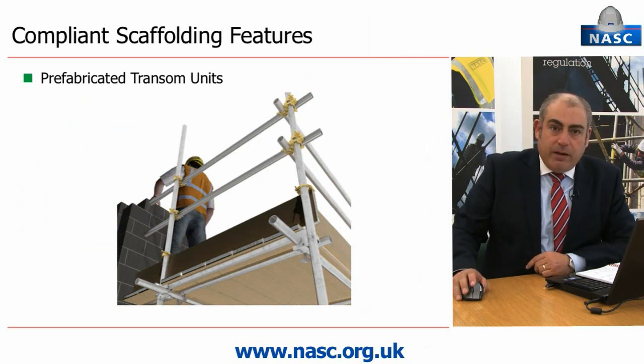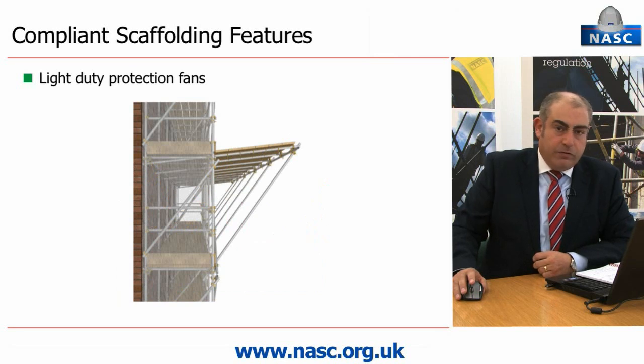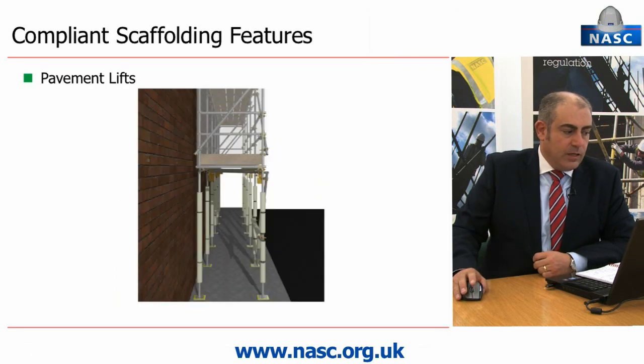The use of prefabricated transom units within independent tied scaffolds, which are commonly used. Light duty protection fans for falling object protection. Pavement lifts up to 2.7 metres. Note that pavement gantries are still classed as a special scaffold and will require design.